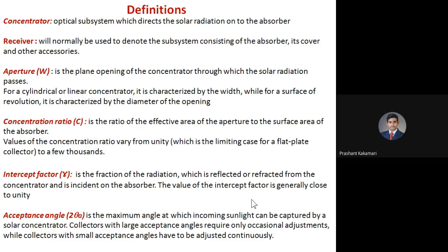Similarly for absorber tubes, say I am using a parabolic trough or a cylindrical parabolic collector or a tower type of solar collector. In that condition, we use a number of lenses or reflectors, or a parabolic trough or cylindrical parabolic trough, which can concentrate the energy received on a larger area and reflect it back to the absorber tubes.